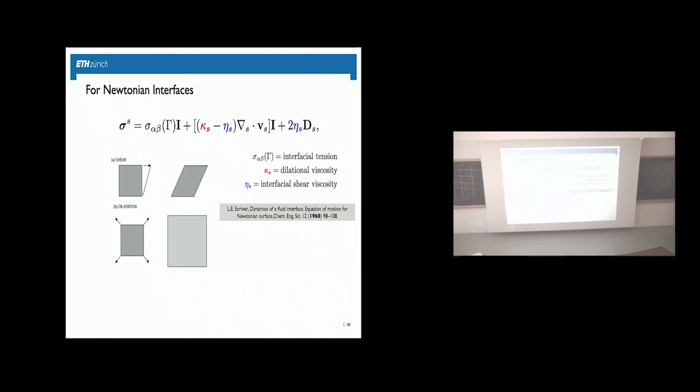They both come from the microstructure, but they're not uniquely related. Different microstructures give different values. It's like the Poisson coefficients. If you have different types of microstructures, if I have time, I will give you one example. They're not linked. For a given material, they are linked, but they're not uniformly linked. There is no thermodynamic relation between the dilatational viscosity kappa and the shear viscosity.